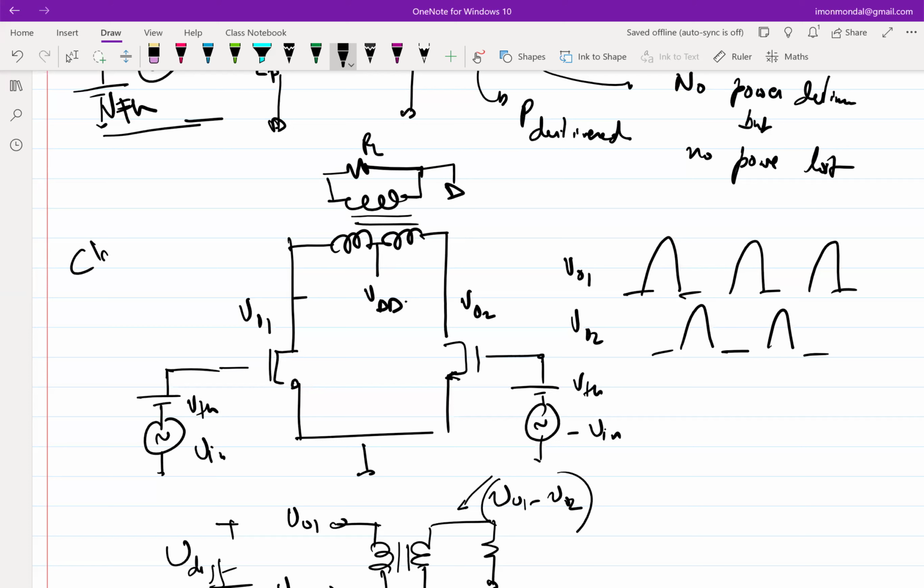This is a class B amplifier where only one half cycle conducts from each of them and you combine the currents, right, to increase efficiency. I will show you the calculation. Have you done class B amplifier analysis before? No. So as it turns out, you get a theoretical maximum efficiency of 78%. That to some extent should make sense. It should actually at least have higher efficiency, right? Because of the reasons that I talked about leading up to this. Okay. Fine. We'll stop here. Thank you.